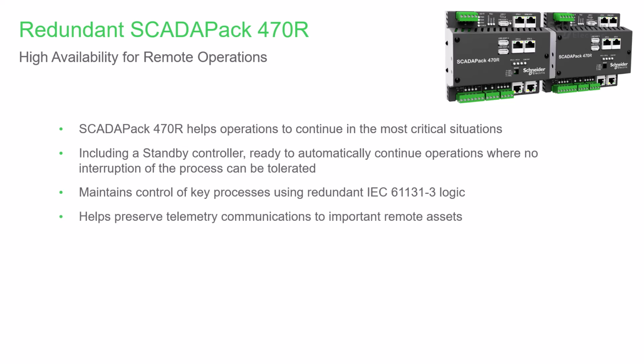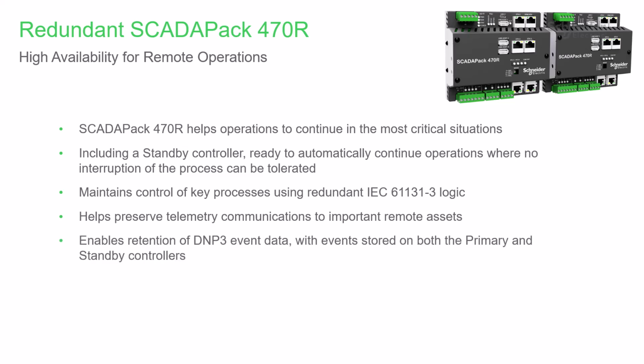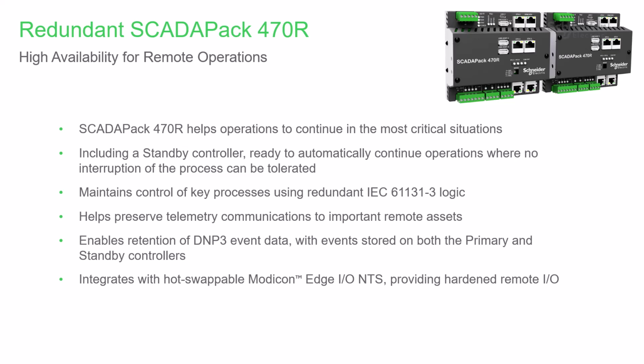A SCADAPack 470R installation helps to preserve telemetry communications to important remote assets. This enables the retention of DNP3 event data, with events stored on both the primary and standby controllers. And 470R can be integrated with the hot swappable and hardened Modicon Edge I/O NTS Remote I/O.